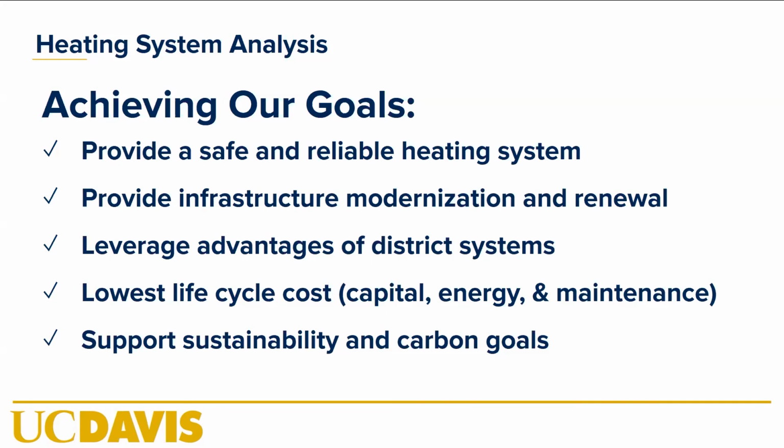Ben asked one about implications for the opportunity to install more solar capacity on campus. If we have this heat pump system now doing heat recovery, our electrical usage is going to go up, especially in the winter. And so the opportunity there is with the storage, we're going to be doing heating storage and chilled water storage, to potentially run our heat pumps and run our chillers at times that we can leverage our solar PV system.